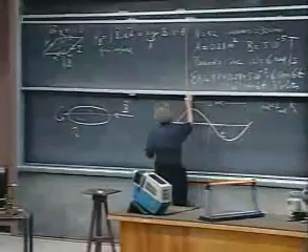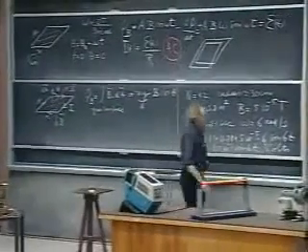You have a permanent magnet, and you rotate conducting loops, windings, in that magnetic field. The higher your magnetic field, the higher the EMF. The faster you rotate, the higher the EMF. The more windings you have, the higher the EMF. And the larger the area of your loops, the higher the EMF. As you can see in the equation that I keep hiding. That's where it is.